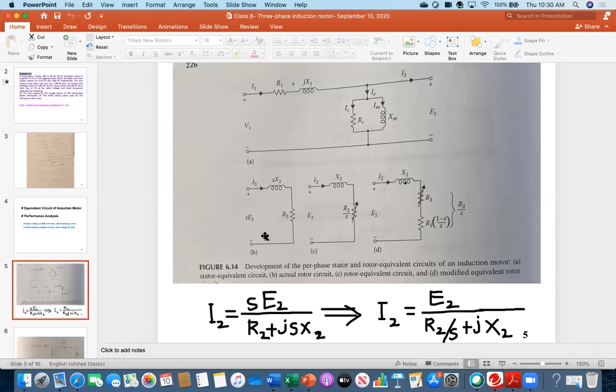If you assume the motor is not running, then okay. Then here you say, from here I am going here. Everybody see the sequence? Can you see that there is no s here? And can you see again here the difference between this one? There is no s here. But then what happened? It was R2 here. Here it is divided by s, by the slip. And I have given a variable resistance symbol.